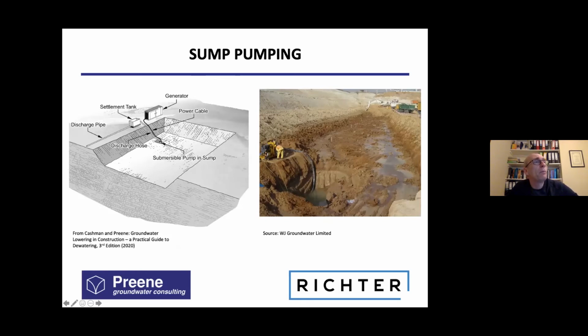You see here we have the pump, a deep excavation, the sump has been dug, and the water is flowing towards us. The first thing you can see is this isn't giving us great excavation conditions. If we wanted to maybe construct high quality concrete in this excavation, it's going to be difficult with the water sitting in the excavation. This could actually be improved, that maybe if they dug a narrow trench down here to direct this water more directly to the sump, that would make this better, but it's still not going to give perfect conditions. So if we needed better working conditions in the excavation, maybe we could have thought about switching to a pre-drainage method that can give you better results.